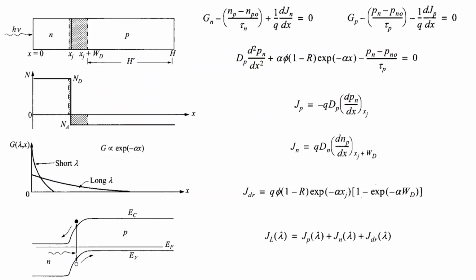So here, once we understand how solar cells work, we have three contributions, three types of currents: two diffusion currents of minority non-equilibrium photogenerated charge carriers from the N and P type regions, and one drift current. So that's our PN junction under illumination, some asymmetric PN junction, where we have mostly the depletion region on the P-type side of the semiconductor. That's the profile for doping concentration distribution, and this is the profile for photogeneration.